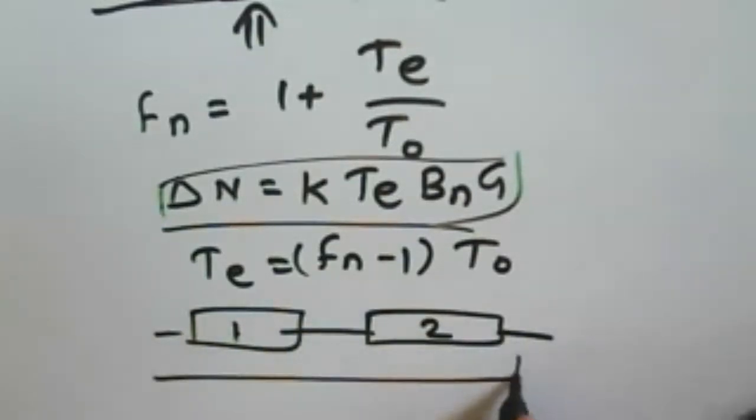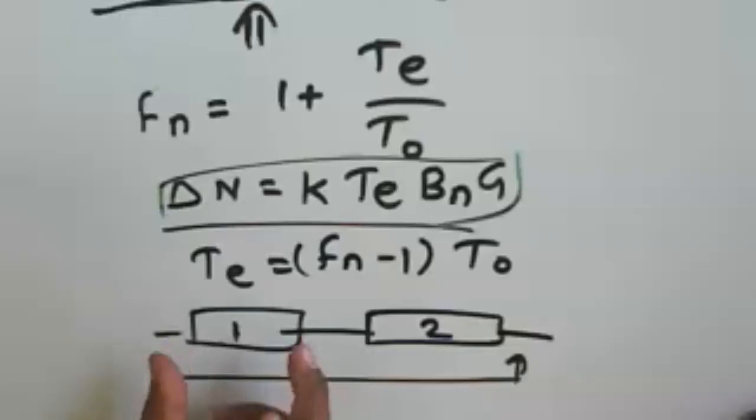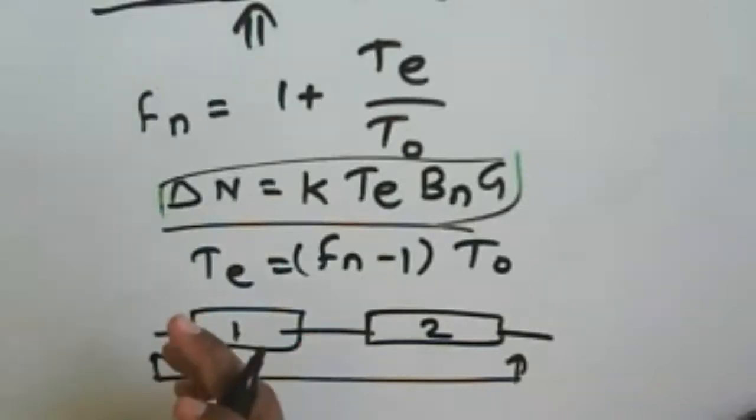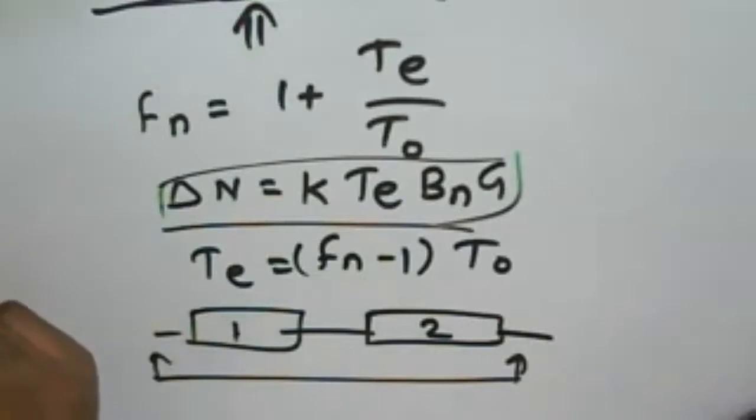But when we are calculating the overall system noise temperature, it depends upon the effective noise temperature of each and every block of the receiver as well as the effects of the antenna temperature.